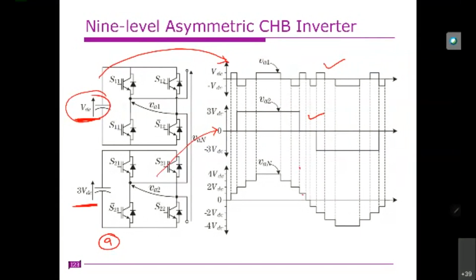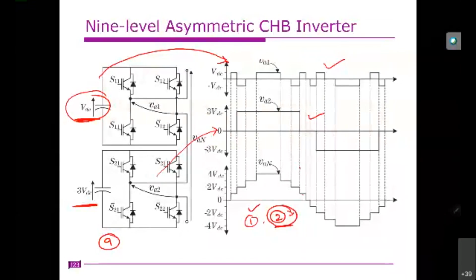So your question is, there are different ways. In the case of 2 bridges, obviously the first one, which has the highest rating, will operate at square wave, and for the second one you have only one bridge. That means it operates with the rest of the modulating signal, that is, the subtraction between the original modulating signal and the square wave. That is the modulating signal for the second one, so there is no confusion.